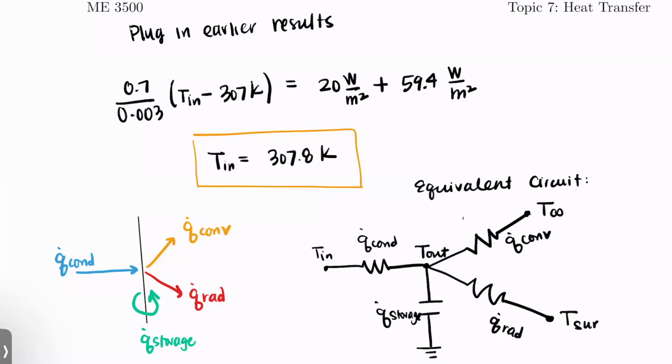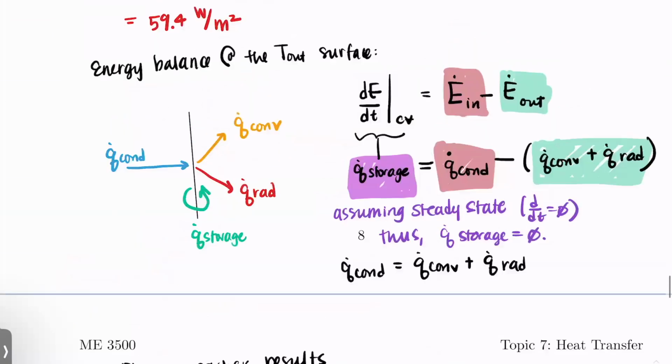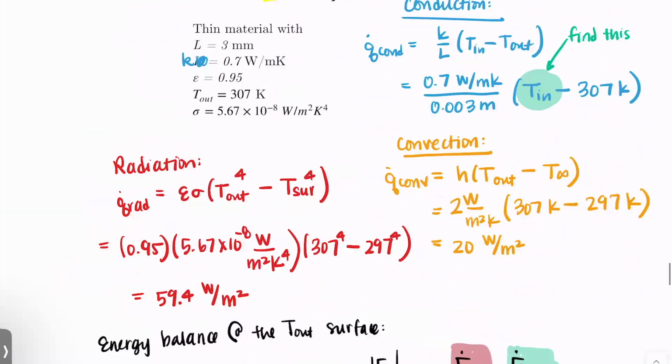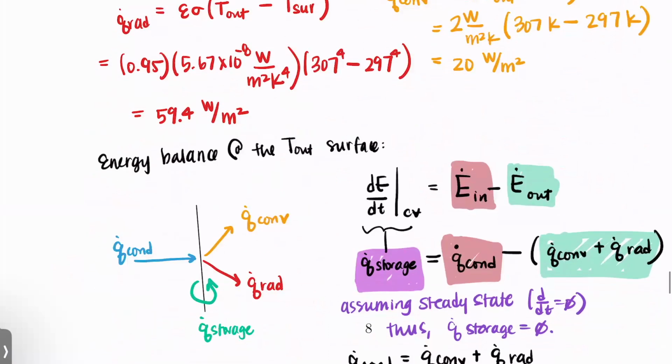just to recap the strategy, essentially we're just using conservation of energy to solve these problems. The way I like to do it is draw a picture always to begin, and then sort out each of your heat fluxes due to the different types of heat transfer you might have, and then draw your simplified energy balance at a point or a surface, and then write out your energy equation like I've shown here, and plug in what you already calculated for the Q dots.